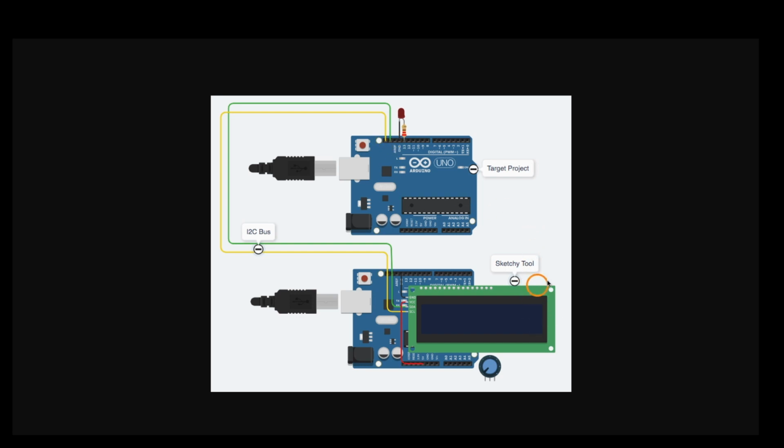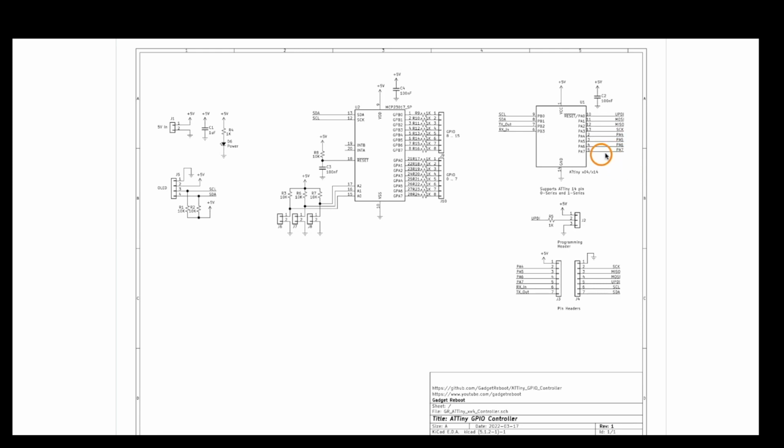And then for the OLED display that I'm using, I am not connecting it to the same I²C, because if my target hardware also happens to use that same OLED at the same address, I don't want to interfere with it. So I'm going to be using other regular GPIO and using another library to bitbang I²C over to an OLED, and it won't interfere with the other I²C.